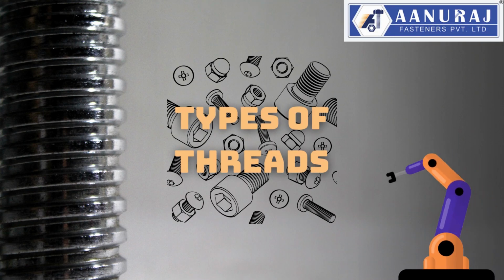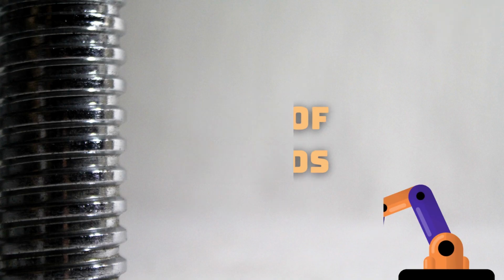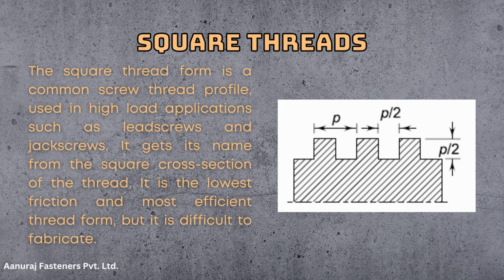Types of threads. Square threads. The square thread form is a common screw thread profile used in high-load applications such as lead screws and jack screws. It gets its name from the square cross-section of the thread. It is the lowest friction and the most efficient thread form, but is difficult to fabricate.